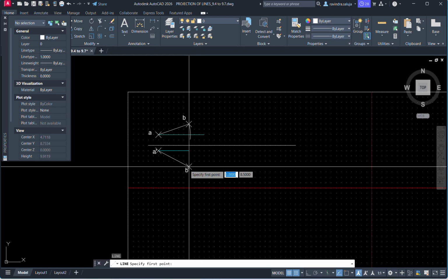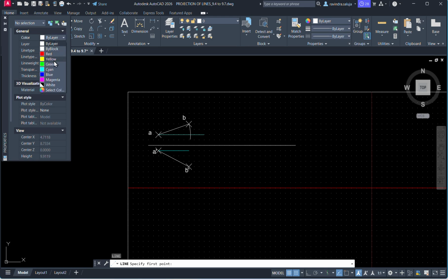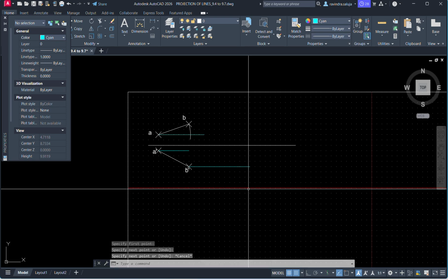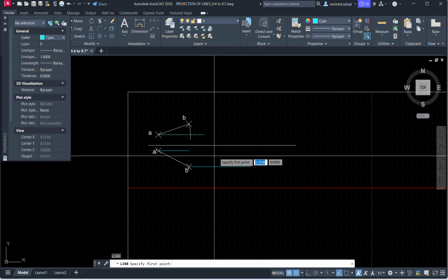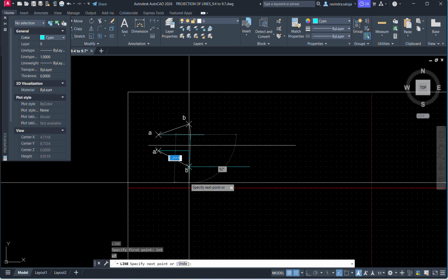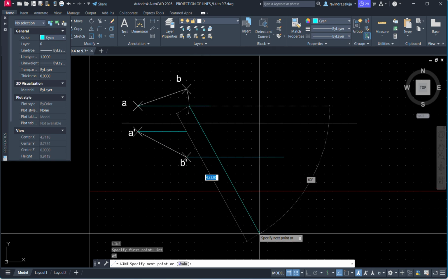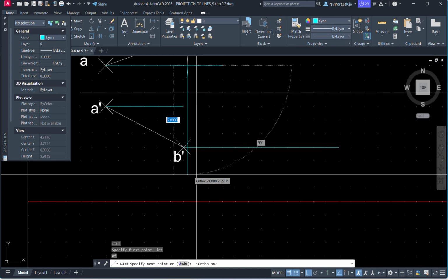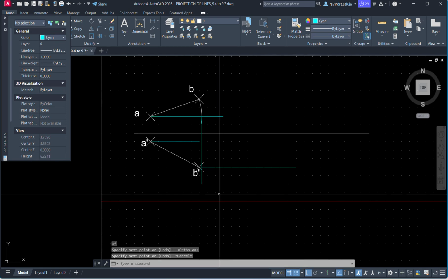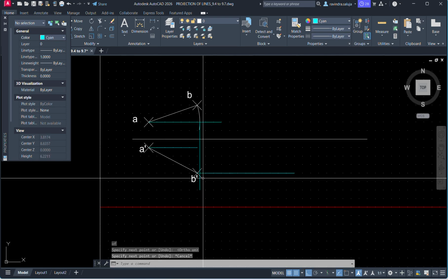Before that, you can draw a helping line from point B, and then project from here. For highlighting this important intersection point, we use INT before drawing the line, and then project. For that, you can use the straight line command. So this is the point you got. There is a very minute difference between the true and the apparent one. So you got the true length point.